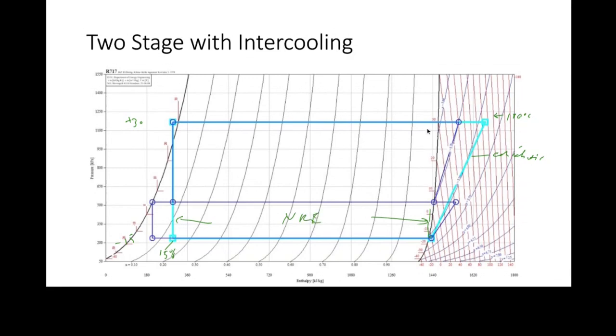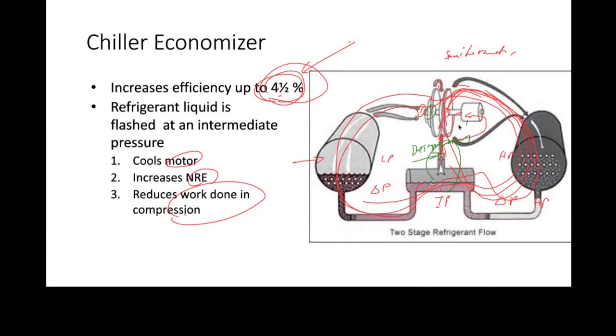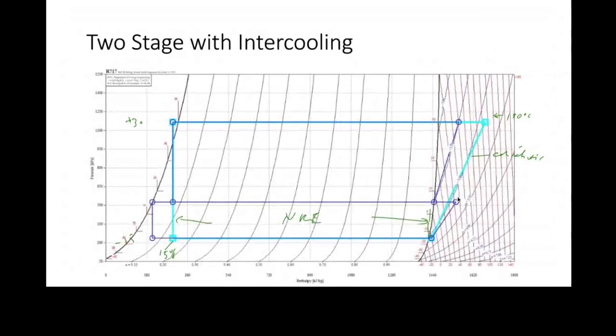And so then with intercooling, we took a look. Well, it's the same as the economizer. It's the same as this thing here. We've got intercooling going on in between stages of compression. So here we've got two stages of compression, stage 1 here and stage 2 over here. And each one of these is adiabatic, so we've got adiabatic compression here, and then intercooling, and then adiabatic compression. So it's not true isothermal. I mean, a true isothermal line would be maybe more like that. Okay, but it's jagged, and it's going to try and mimic that isothermal compression.